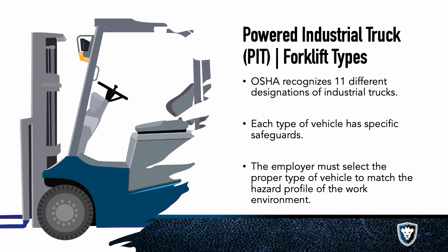So if you're working in an explosive atmosphere where you have LEL floating around or dust floating around that could ignite, you don't want to use something with a high heat output like a diesel forklift, right? You're going to probably want to use an electric forklift that has some of the Class 1, Div 1 or Div 2 encasements for the battery and the engine and all those different parts. So that's really what it comes down to.